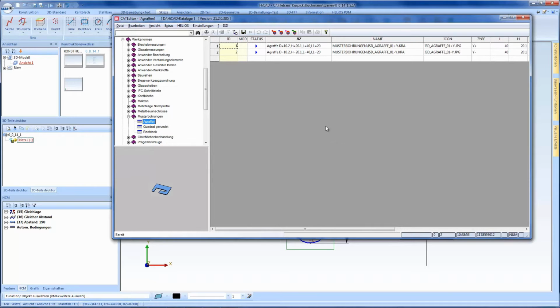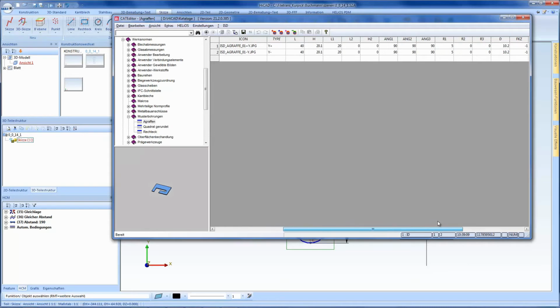It should look like this afterwards. And then I can see, for example, the name, or more importantly, the HiCAD path. So bore patterns in this case, the name of the file .kra, which you've entered when saving earlier. Respectively, the variables are shown which you have to add subsequently in order to be able to control your model afterwards.